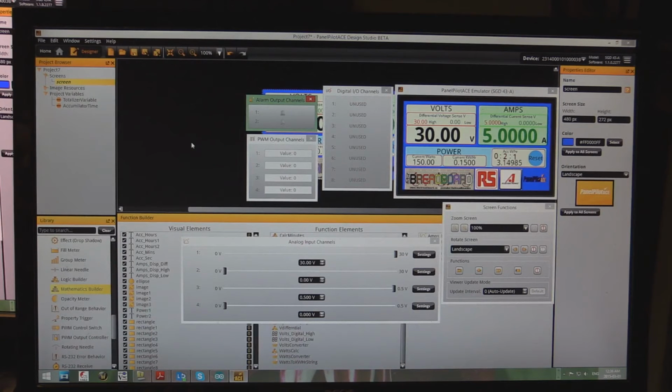And yeah, next video, what we're going to do is maybe enhance upon this and have some relays. I'm going to show you how to drive some relays and various other things using the output alarm and digital outputs, and also respond to maybe some push button inputs, and use maybe the alarm outputs as well as the PWM outputs to drive some power LEDs or something like that through it. It's only 256-bit, unfortunately, so it will be a little bit limited in its resolution.